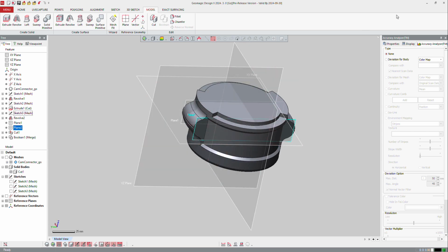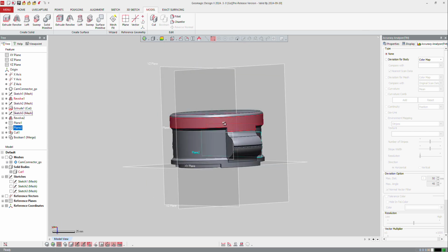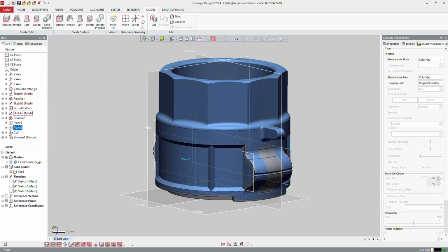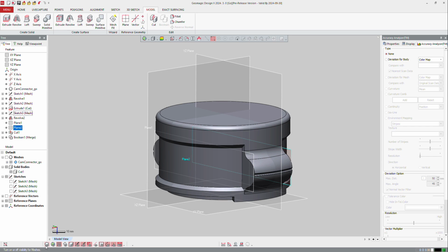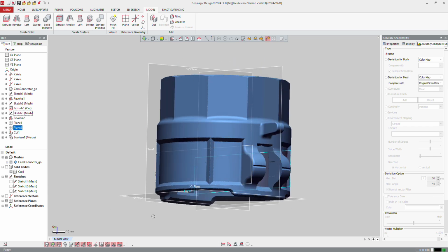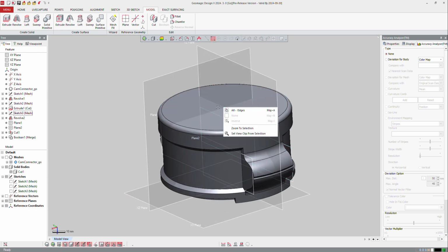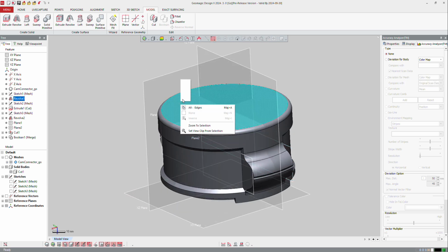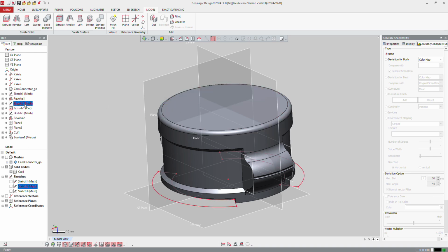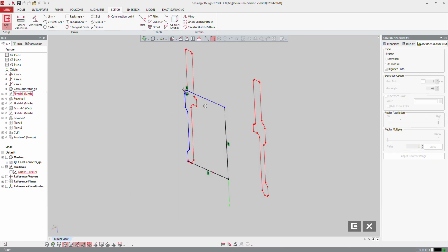Okay, so now I will do the endpoint of that. So the endpoint, the other side is this area. So this area is an extrude. So I will go here, right mouse click on this area on this plane and make a mesh sketch. So I'm not sure. You see that it doesn't propose me anything. So which means that this revolution is not a plane.